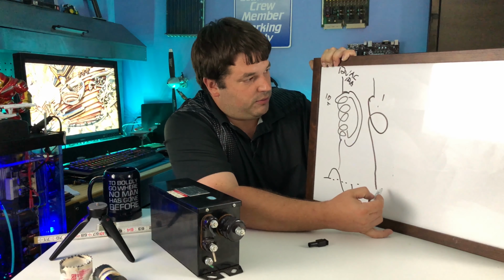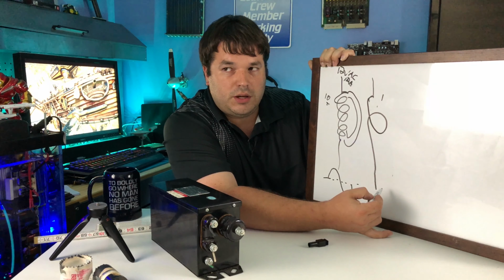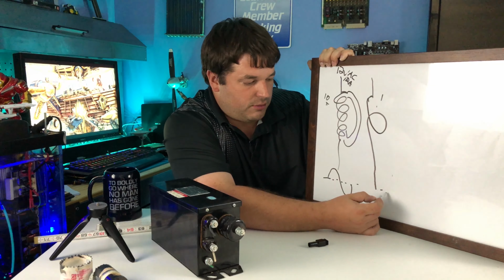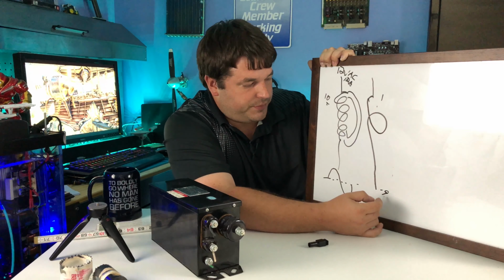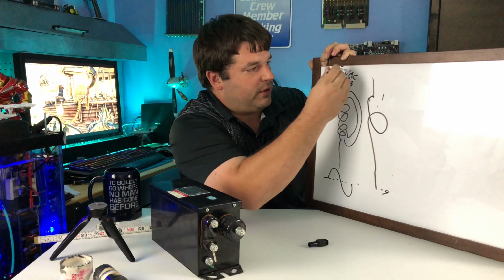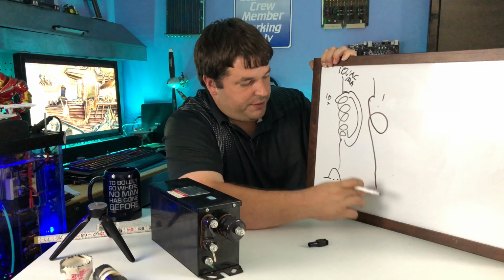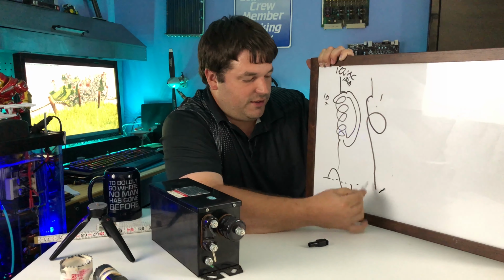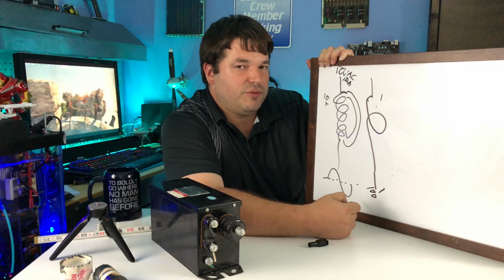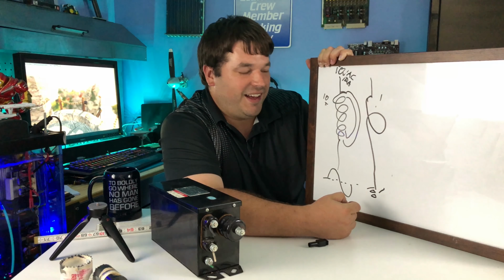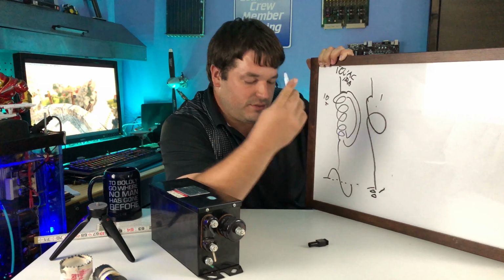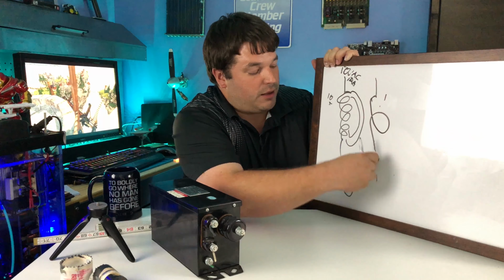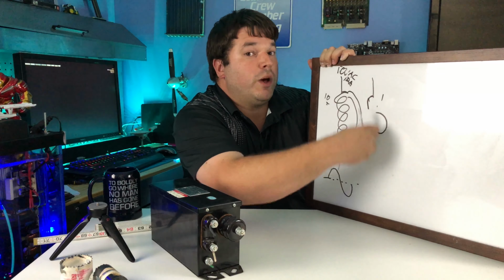Now I only have, it's less than 1, so it's going to be like 0.9 volts or so. I could do the math, but whatever. In fact, I'm going to change this to 10 volts because that'll make it easy. At 10 volts here, I'm only going to have 1 volt there, but I have the potential for 100 amps. I changed the electricity doing so. Now, you say, 1 volt, what good does that do us? Well, 1 volt at 100 amps, you can almost weld with that.